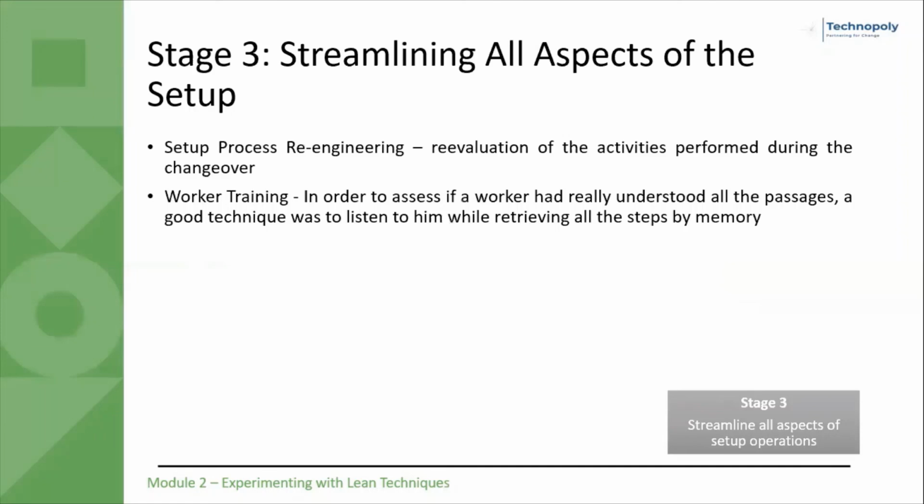For example, collecting the disassembled equipment into a box to be delivered to the shift supervisor at the end of the setup process, with the worker leaving the machine only once. The supervisor successively sorts the equipment and properly stores it on the shelf. In a way, the activities were distributed to personnel involved in the setup to reduce excessive transportation for one person only.